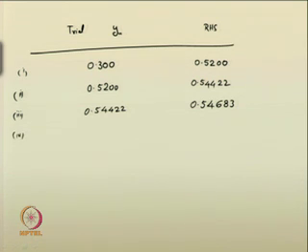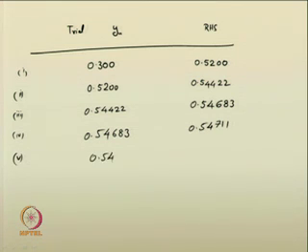If you want to proceed further, in the next iteration I incorporate y n LHS as 0.54683 and the corresponding RHS term I am getting as 0.54711. If you want, you can again go for an iteration, but it is almost converged. In open channel flow, in such large scale problems, you need not go further, you can consider that 0.547 could be the answer. So, I am not going further.